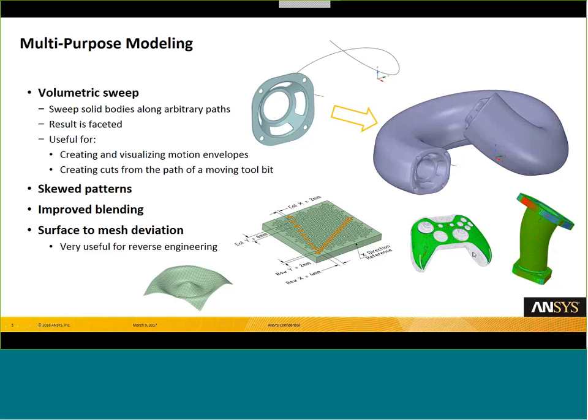What we've added now in this release is the ability to actually see the difference between two models. You can create just a small surface on the geometry and see the deviation between them. So as you're starting to recreate some geometry over the STL, you can intermittently see how close you are instead of waiting to the very end to see the difference across the whole model.